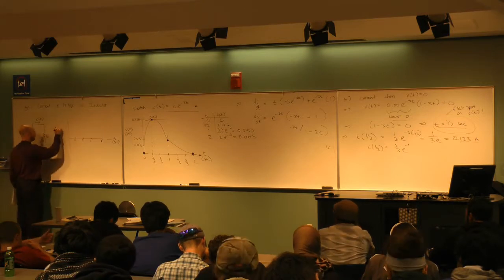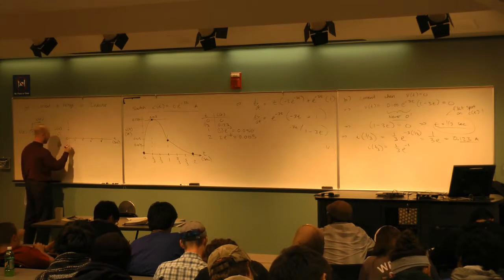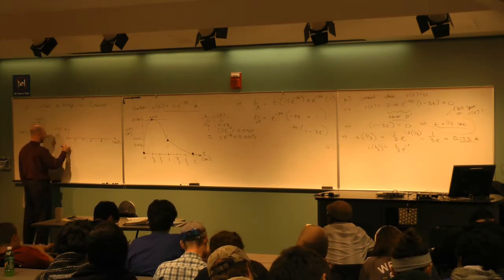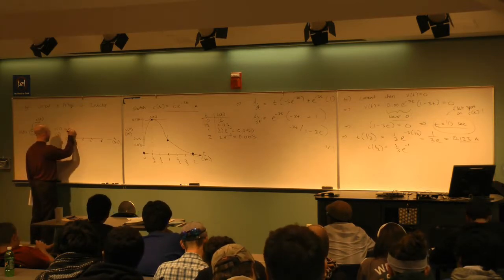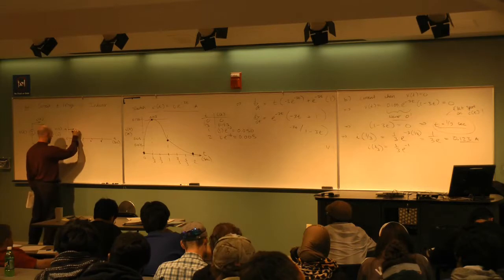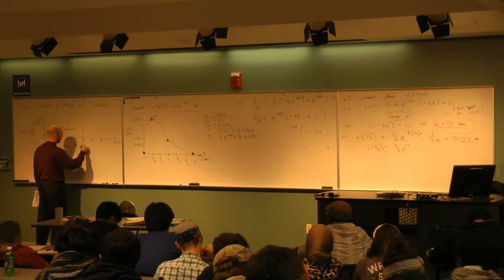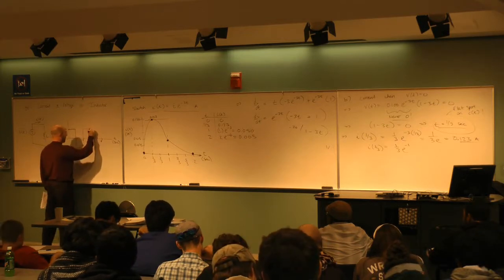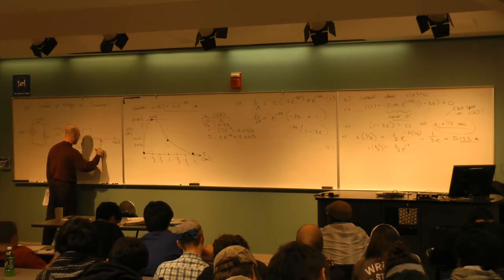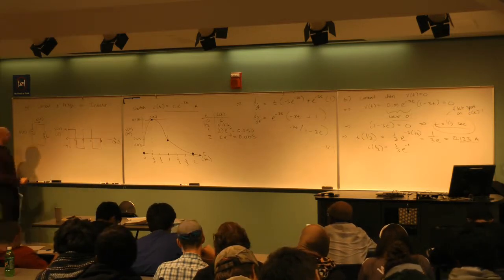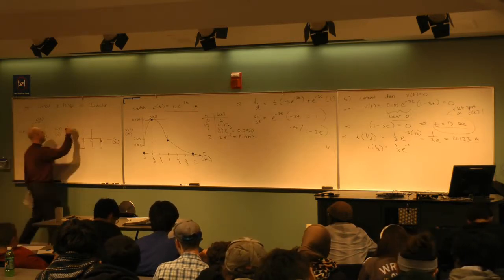And this is going to be the voltage V of t in volts. 0 right here, and we'll just go plus or minus 9 volts. So for the first 2 seconds, we're going to connect it to the positive. Then we're going to switch it and go down here to the negative. Then after 2 seconds, we'll come back up to the positive. And then after 2 seconds, we'll switch it back down to the negative. Like that. Incidentally, what kind of a signal do we call that, do you think? Yeah, this is called a square wave.